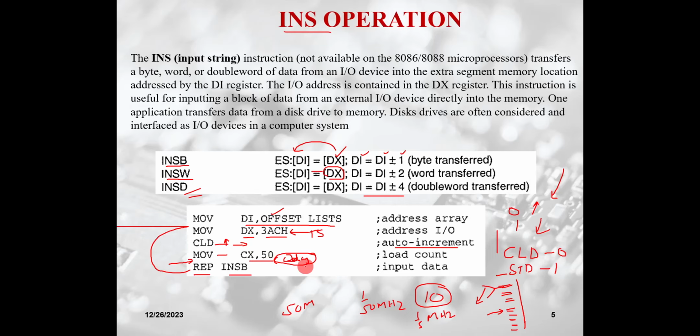Or you could say maybe there are hundreds of temperature sensors, okay. So in that case I want to get this data and put it into one memory location, get this data and put it into this memory location, right, from each sensor. So in that case probably I need to write here, right, and I can increment this data in the dx, right. So every time I can write dx is equal to dx plus 1 or something like that, so that the next port data is fetched from the next port. So those things of modifications we can do.